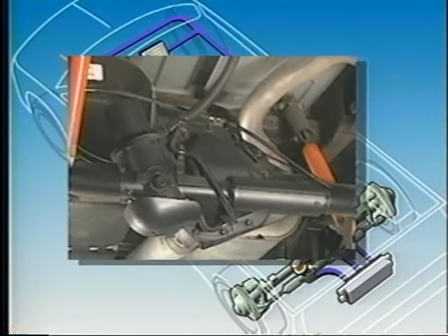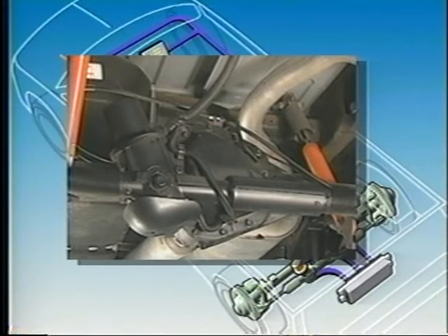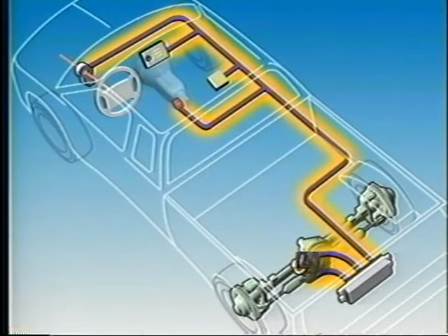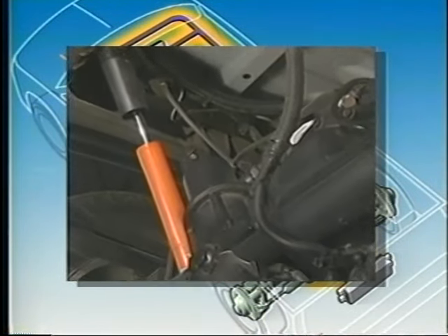The steerable rear axle is located in the same location as the non-steerable rear axle, at the rear of the drive line. The difference, however, is the steerable rear axle includes quarter shafts with steering components on the ends of the quarter shafts. The rear wheel steering control module is located in underbody rear over the spare tire. The rear actuator consists of the tie rods, rear position sensor, steering gear motor, and rack and pinion boots, and is located behind and above the steerable rear axle. Finally, the rear wheel steering wiring harness is a subcomponent of the main vehicle harness.